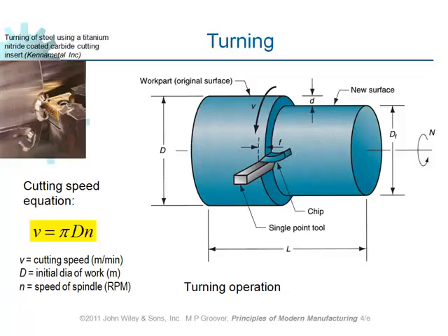And as you can see, this cutting tool itself has got a linear motion which is called feed, and F stands for feed. For every rotation of the workpiece, the cutter makes a specific amount of motion along the feed direction, which can be adjusted on the machine.